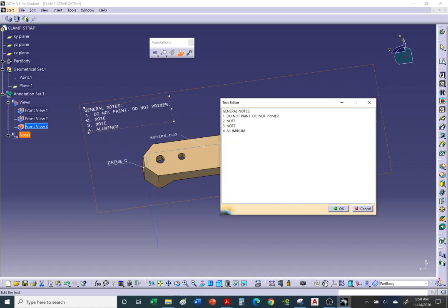And I'll say this time I'll use 7075, which is a very strong aluminum alloy. 7075. Typically in aerospace, when you're machining structural members, we go with the higher strength aluminum alloy, 7075. And the temper, I think T651 is a common one.